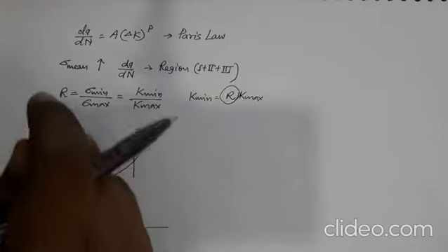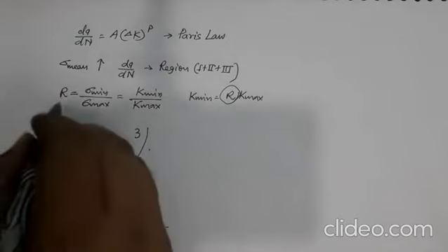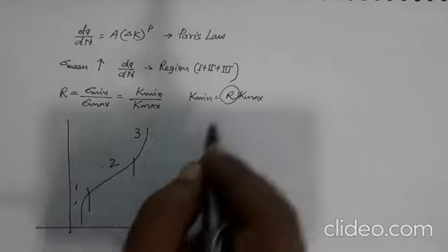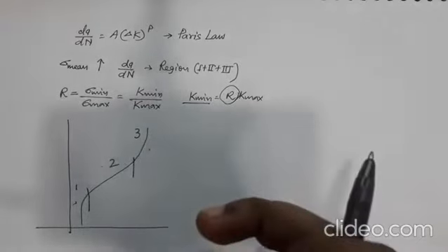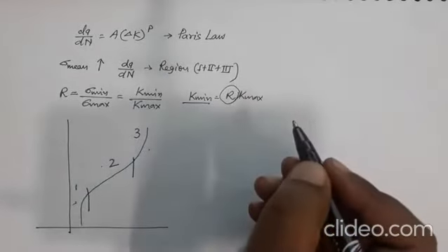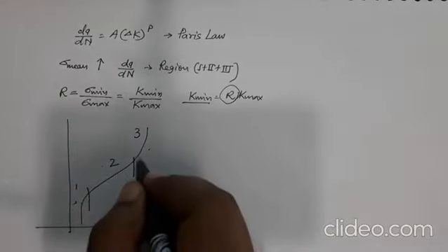So it will become easier for the crack to start growing if you increase the R ratio, and also the catastrophic failure will be much easier because my sigma minimum or K minimum, so my lowest amount of stress intensity factor, is much higher if I am increasing the R value, right. But the effect of that on the second part is not very high.